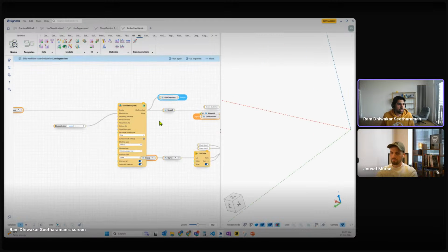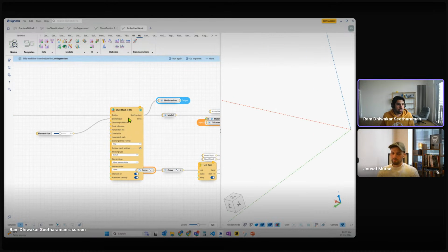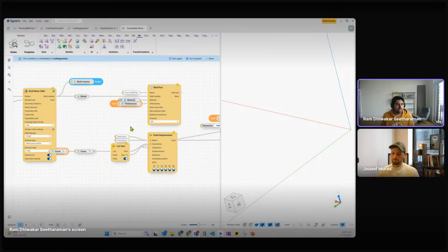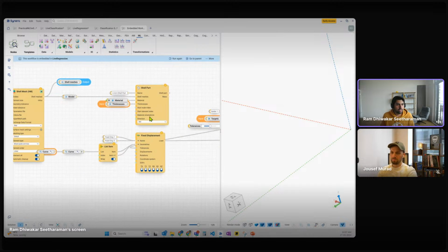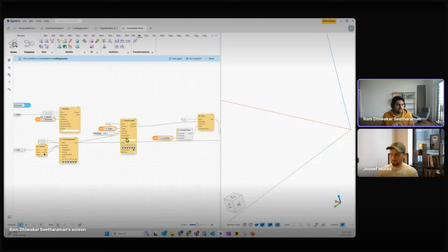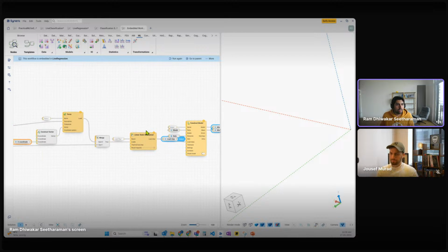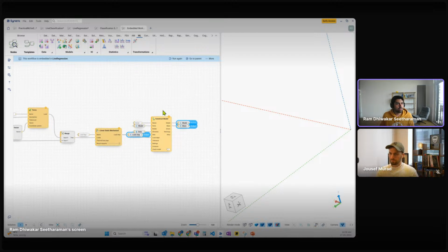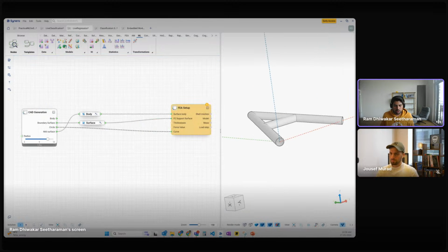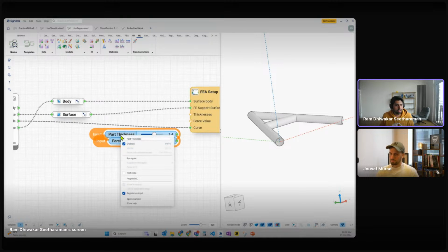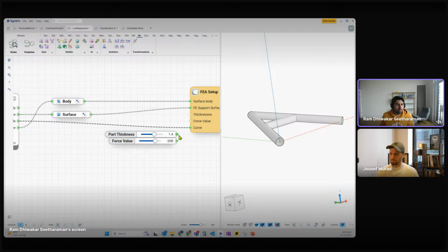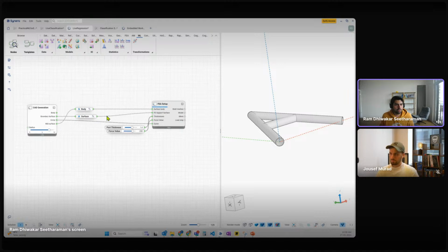What this is doing is basically taking the body. I use HyperMesh to mesh it. I declare it as a shell part. I apply some fixed displacement. I can also build my RBEs, apply the forces, do a linear static step, and construct this model, basically build a load step. Therefore I'm also going to take some parametric values here. This will be my thickness, and this will be my force value because I'm giving it in minus Z.